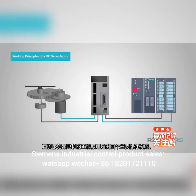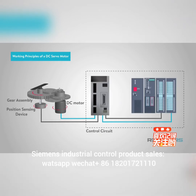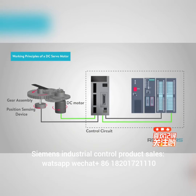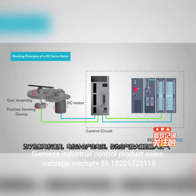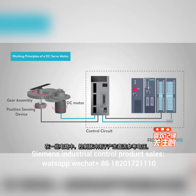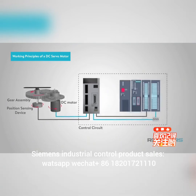The working principles of a DC servo motor are the construction of four major components: a DC motor, a position sensing device, a gear assembly, and control circuit. The desired speed of the DC motor is based on the voltage applied. In order to control the motor speed, a potentiometer produces a voltage which is applied as one of the inputs to error amplifier. In some circuits, a control pulse is used to produce DC reference voltage corresponding to desired position or speed of the motor, and it is applied to a pulse width voltage converter.